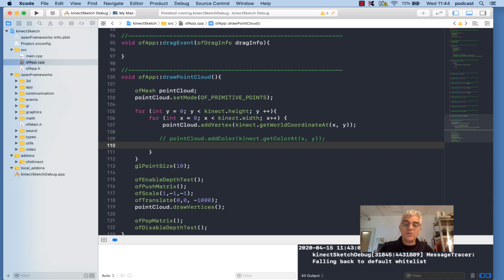And I'm going to use HSB, which is a hue, saturation, and luminance value. I could use RGB if I wanted, but HSB is easier because I can keep the saturation and the brightness the same and just change a hue. So I can go through a color palette, but keeping all the colors similar, whereas with RGB it becomes a little bit more complicated because of how the color space is made. I'm also going to be doing a video about that.